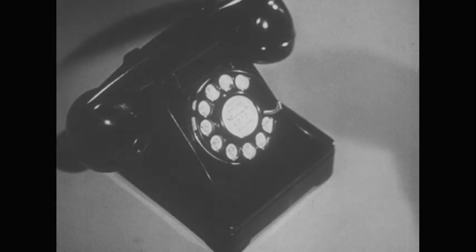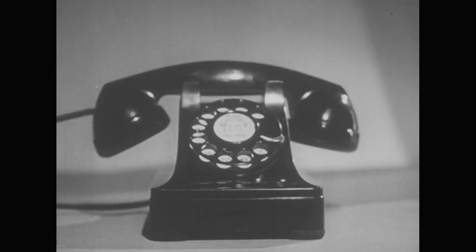Or suppose you want to make a drawing of this telephone. You need a true view of the dial, of course. But the front view shows the dial foreshortened. That is, it makes the circle of the dial look flat. The top view also shows the dial foreshortened. And the side view shows the dial as a line.